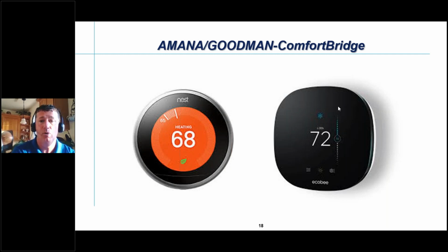A lot of people don't know what's going on with that right now. And I'm here to tell you, this is the way that we should have handled modulating equipment going forward, because our thermostats for communicating equipment keep getting more and more expensive. Well, now we have communicating equipment that doesn't care about a communicating thermostat. It just wants a switch, and it's going to modulate its equipment based on the amount of time that switch is being closed or open.